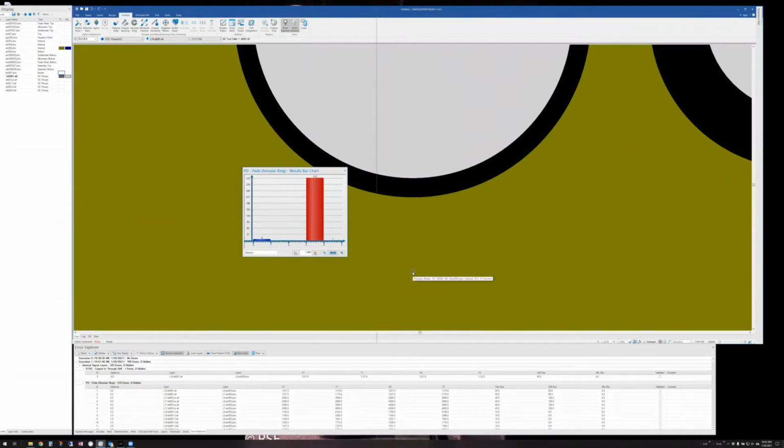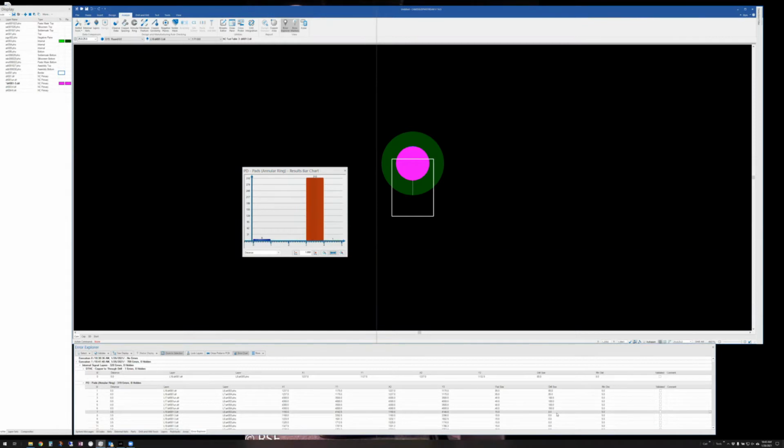All right, so we're in a 160 environment. We only have the one annular ring check, right? But we can look and see, well, wait a second, and we'll just click on one here so you can see it. That was an 8 mil drill with a 15 mil pad. Well, that's a via, obviously, so I'm going to teardrop those anyway. So you know what, 3.5 is enough, and I'm just making the decisions here. 3.5 is enough annular ring. I can right-click and validate those. So those errors go away, actually just the one, unless I'm choosing the header here, so let me do that.